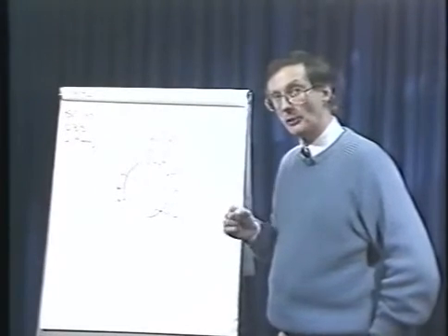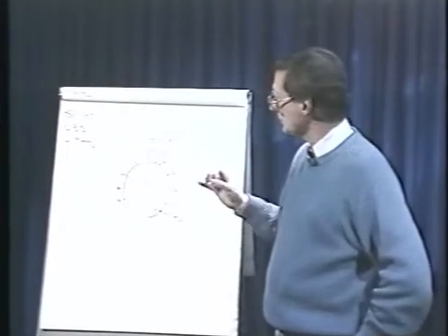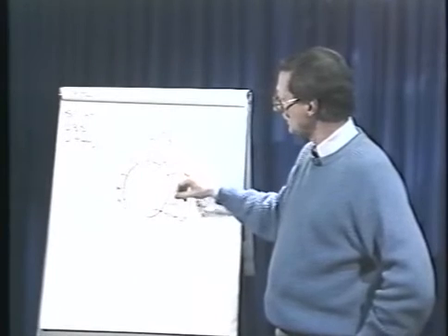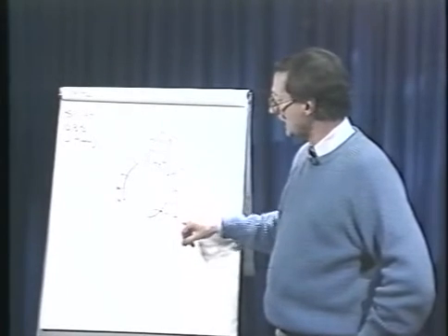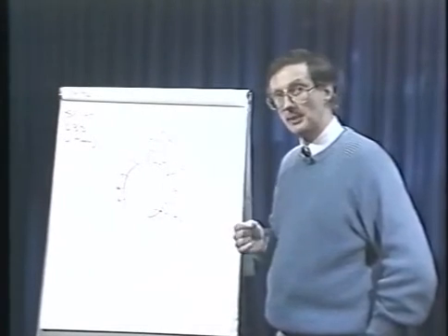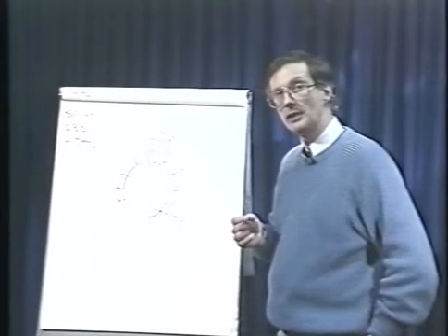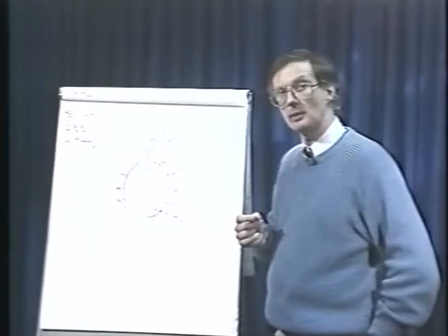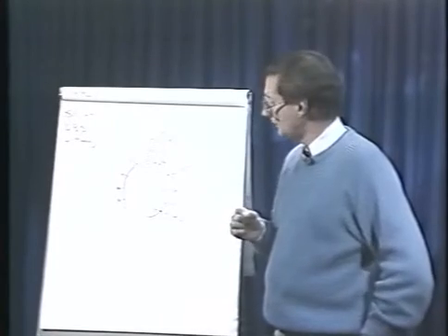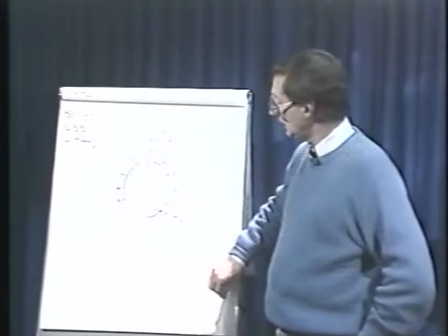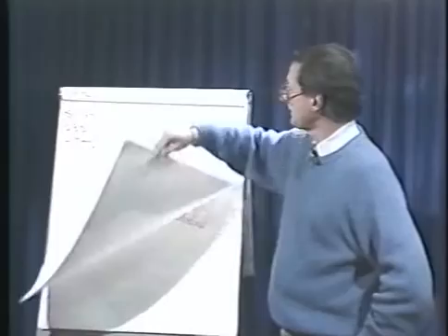Now the problem with 035 wires is deposition. As we'll see later on, we're going to be working at relatively high currents but at about 50% less deposition than we'll be achieving with an 045 wire. The ideal wire, therefore, for spray transfer is an 045 wire.